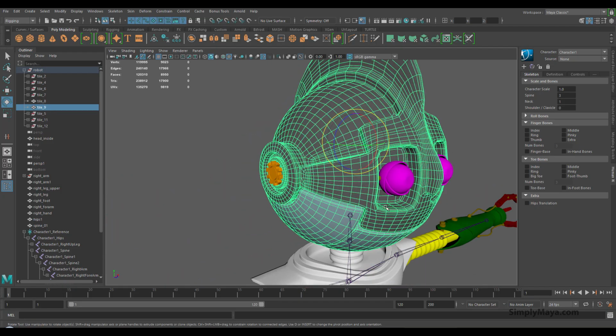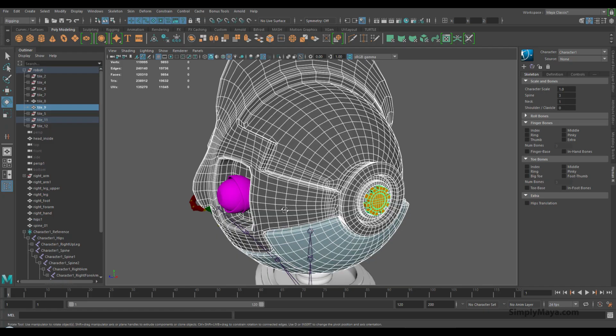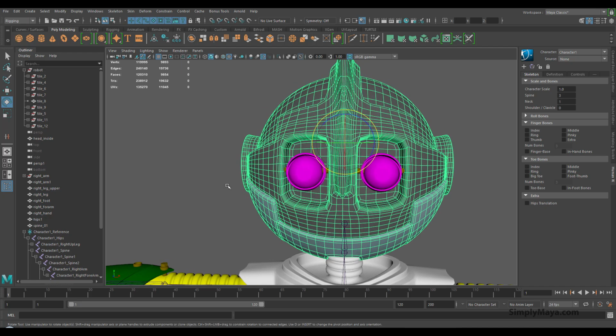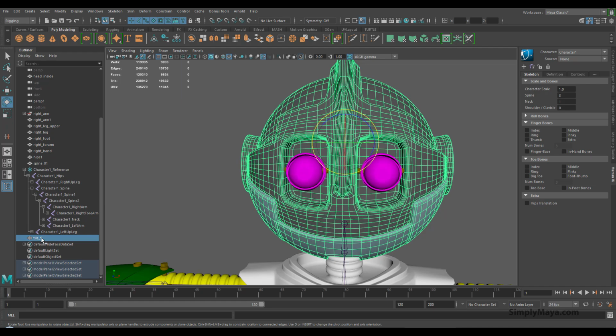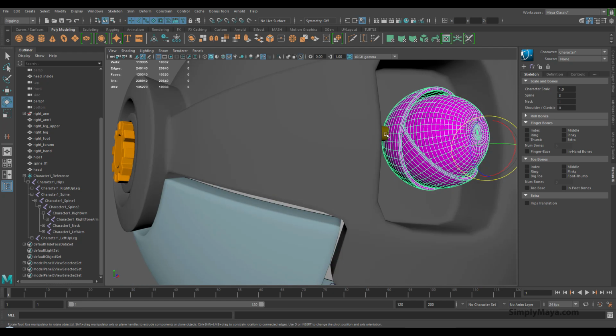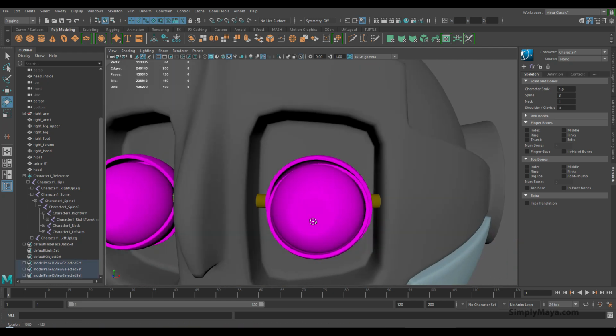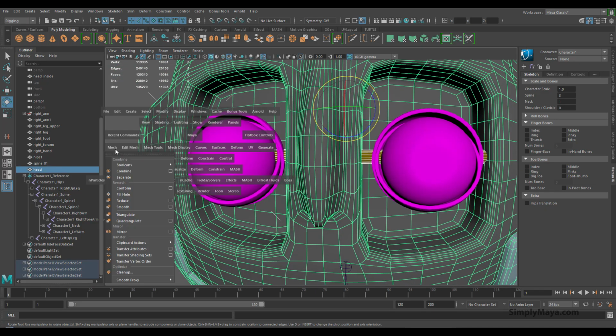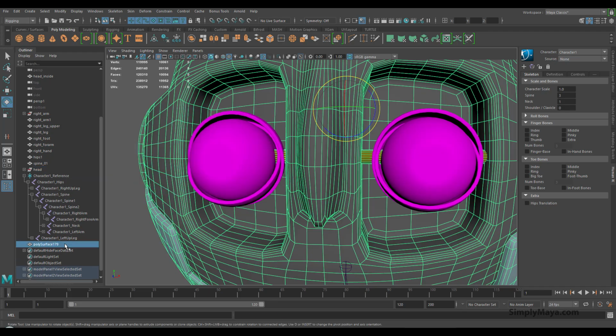And for the head, I'm going to join this one and this one. So I'm going to do a mesh combine. Okay, and that's combined our head. And let's find that geometry. So where is that? We'll call this head. And I'm going to pull this one up. Now the eyes I'm not actually going to combine. Actually in our head should have gone these guys here as well. So let's select those, select the head, do a mesh combine again, and a rename just to head.